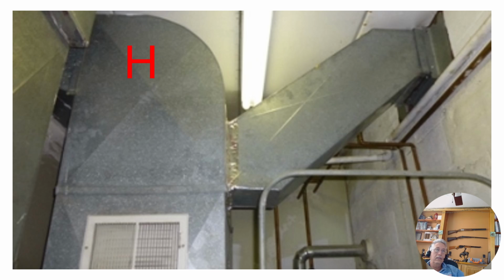H is heat. So this doesn't meet code around these parts anymore. This furnace was in the warehouse where you could pull a car in, so I believe that qualifies as a garage. You could pull a car in there and leave it running, and then your furnace, which is your heat source for this area, would suck the carbon monoxide in and blow it through the rest of the building. So this would have to be sectioned off in new construction, but back when this was built in the 50s, I believe this was acceptable. And there's the ductwork going through the ceiling. Remember, it was in the floor and they abandoned it, and now you can see where it goes to the ceiling here.